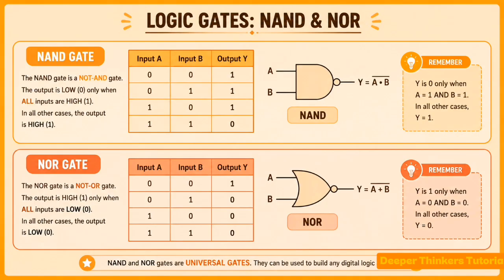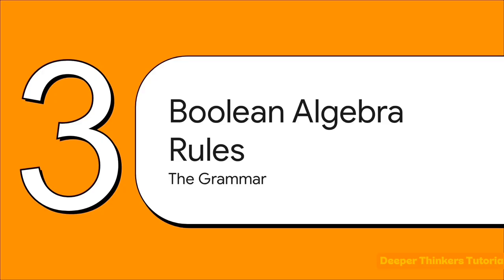So if you want to make it easier for yourself, you can just draw the AND gate, then anything that the output will give you, just do the opposite of it. You understand? After drawing A and B, the two inputs, you invert all the things that were supposed to come out for AND, and you get NAND. Then invert all the things that are supposed to come out for OR, and you get NOR. So that's it.